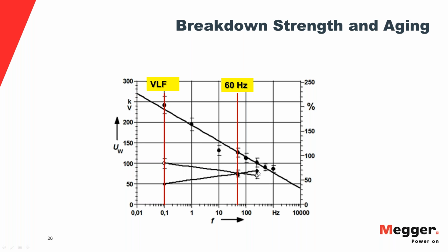But as you can see, this curve is frequency dependent. So if you are worried about VLF testing, you had better worry about your 60 hertz test sets, or whatever you do at power frequency, because you see the safety margin is much, much less at power frequency than at VLF. If you think that VLF is overstressing the cable, then look where you end up at 60 hertz. Just to address this misconception a little bit here.